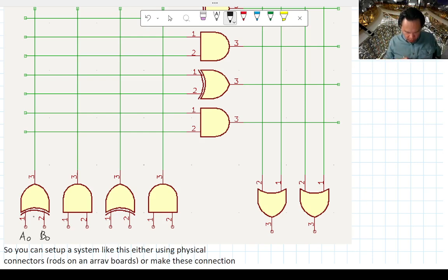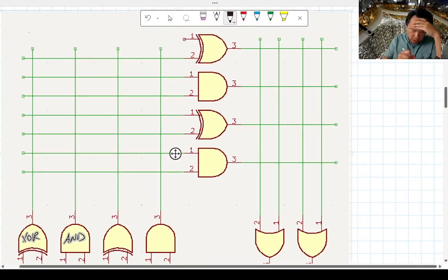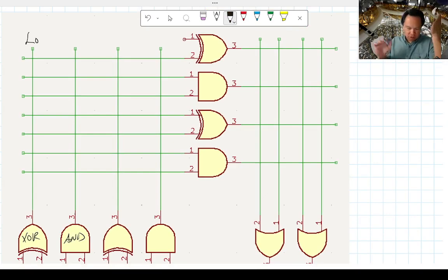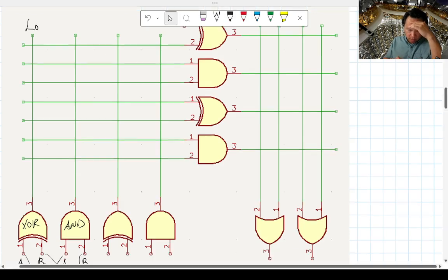And then you put that input into the XOR gate. I'm gonna write this up here. And the AND gate. Okay, so the way you would do this is you just connect these two wires together, right? Like that. Okay, and then you have a single input that you can put. Okay, so the XOR gate output for the 0th bit, actually that's the least significant bit output, so you can just directly take that, right?